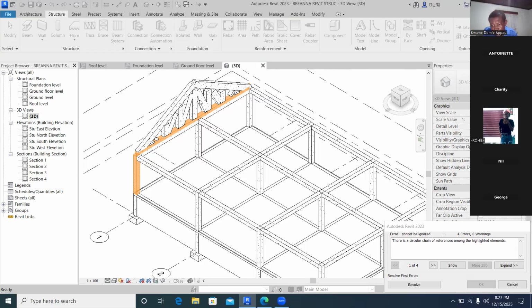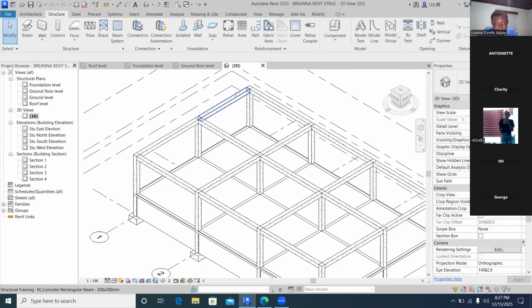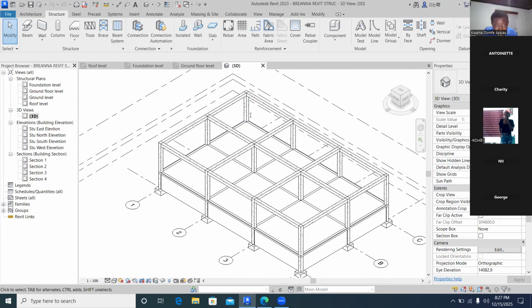Click on cancel on the download board that's on the right. When I cancel it, it will disappear. All the trusses go. Do you know the problem? The truss is a design element, and it uses structural members. Currently, the framing members of the one you chose use concrete, the one you used for the beam. That is why it gives that warning. So we need to change it to either steel or timber. Let's do that right now.